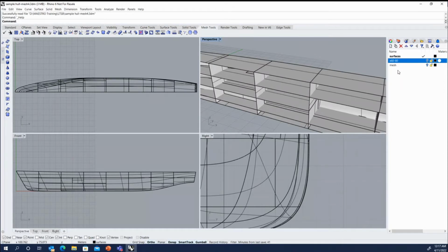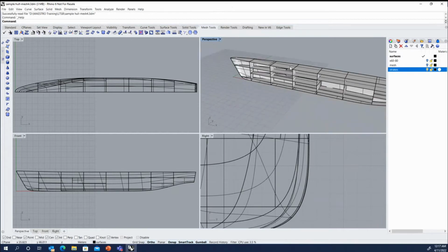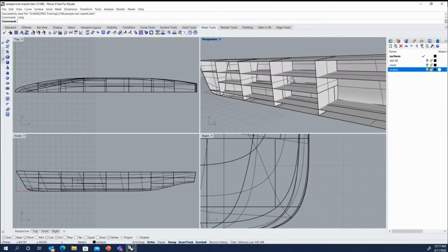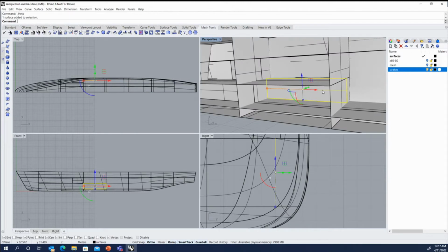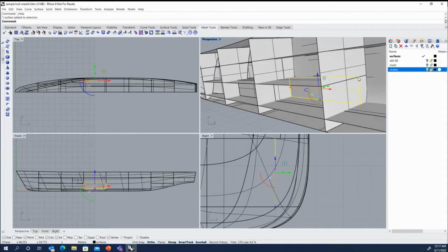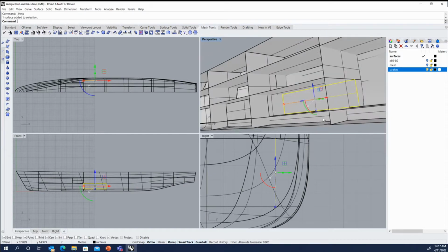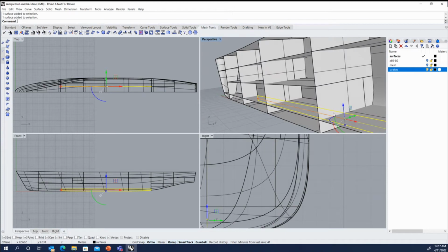So I'm going to turn off that section, and I'm going to make a new layer, and we'll call it strakes. And we're going to do this portion of the hull here from 20, 40, 60 to 80. Now the decks are at 5 meter increments here, and you'll see there's a bulkhead here to define an outboard tank that we'll build later, and that's 10 meters off center line. And there's a division in the inner bottom here, which is 5 meters off center line.